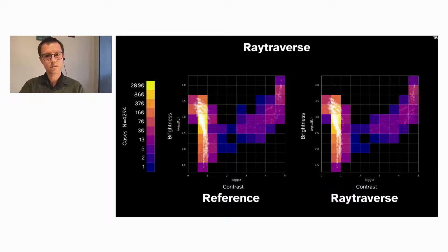The accuracy of this approximation, as the distance from the representative ray increases, depends on how quickly the scene is changing. The ray traverse sampling methods space samples according to this variance. Working in tandem with sky and sun coefficient methods, a much smaller set of samples can be used to reconstruct a nearly identical distribution of conditions to a set of high-resolution point-in-time simulations.